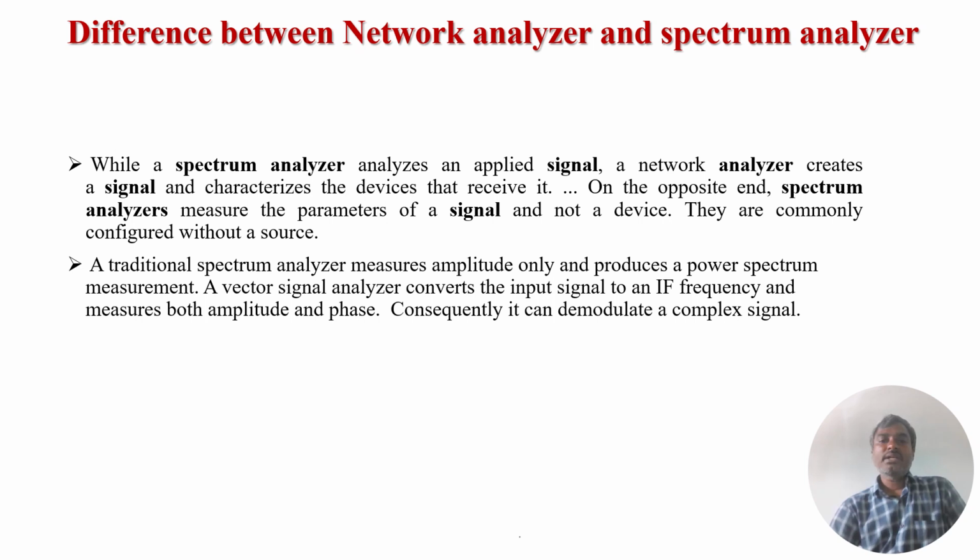Traditional spectrum analyzers are used to measure amplitude only and produce a power spectrum measurement. A network analyzer converts the input signal into an intermediate frequency and measures both the amplitude as well as the phase of the signal.